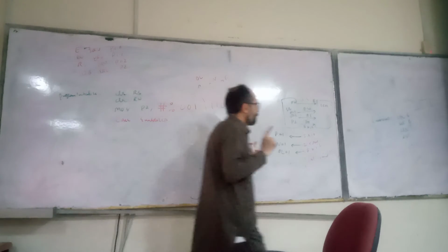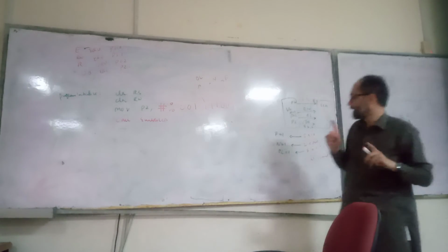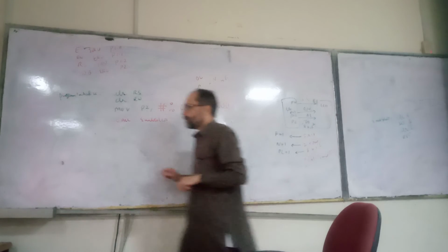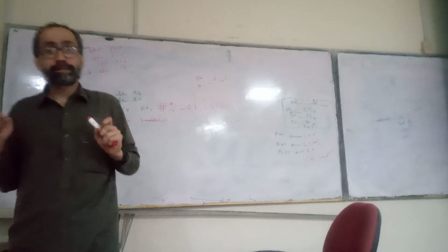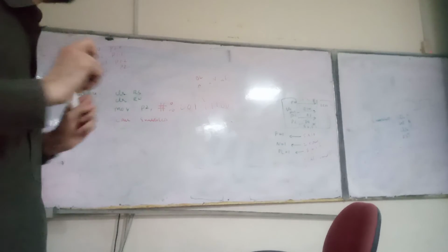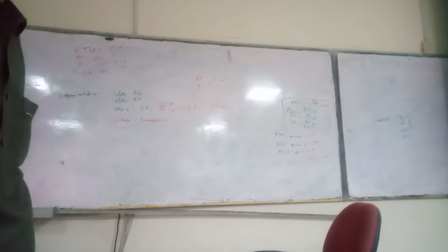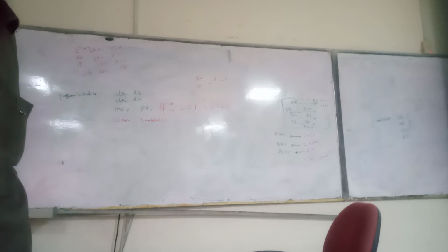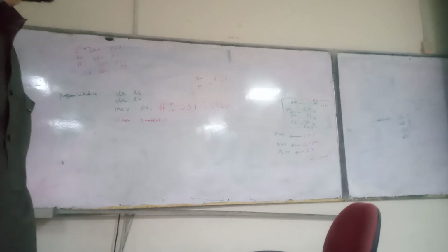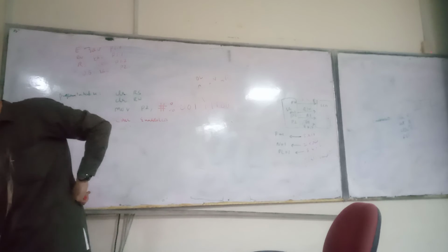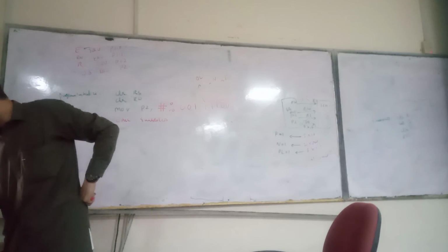Now this is also one specification that I did not mention here. Whenever you display some data, it should always move to the right directly. So ID should be 0 for the right shift config.